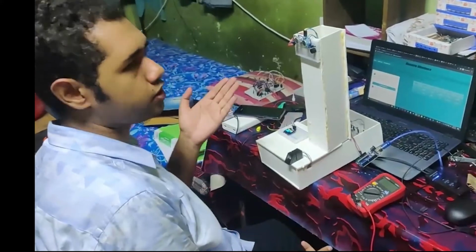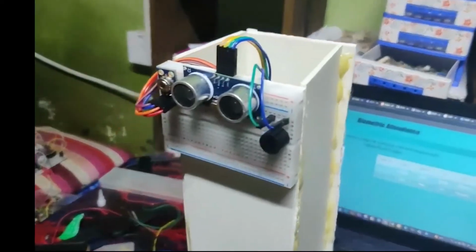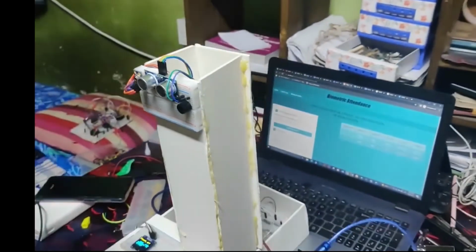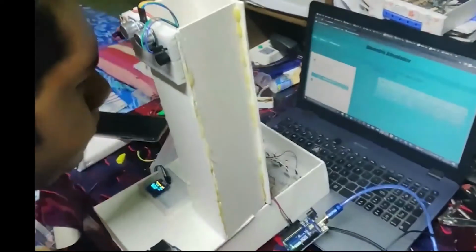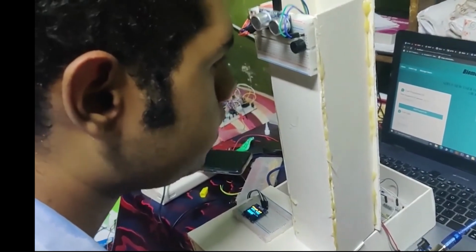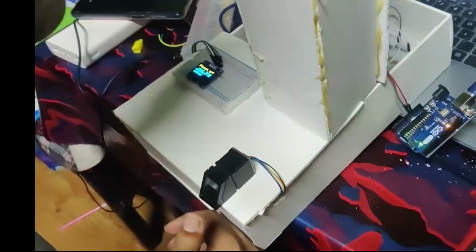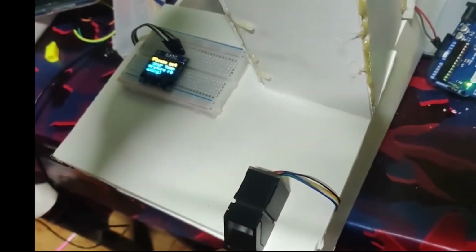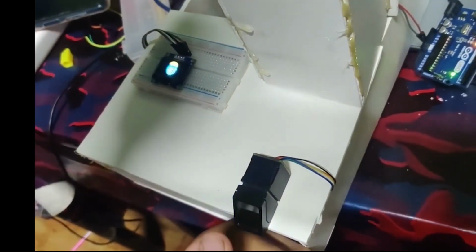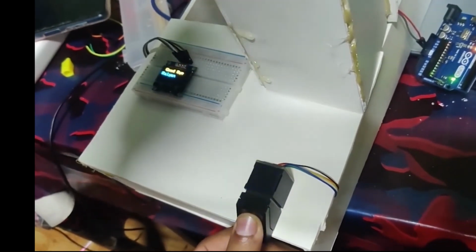As we can see, there is a sonar sensor and a temperature sensor close by. Sonar is used for only ranging purposes. Now I'll bring my forehead near the ranging, and then what will happen is that the sonar will try to detect the surface, and once it is in an adequate range, it will measure my temperature, and if it is below a certain threshold, it will let me put in my fingerprint.